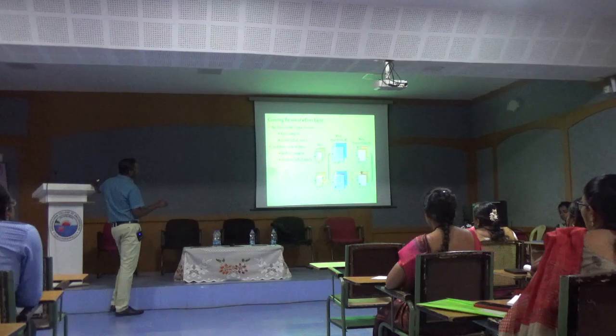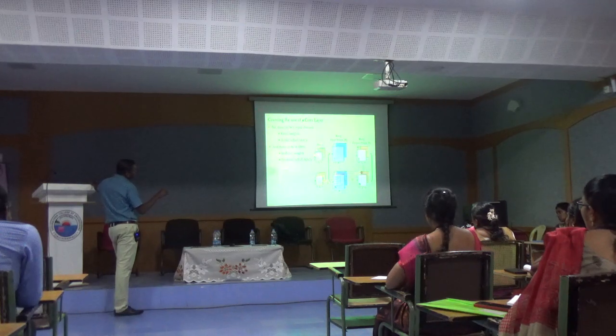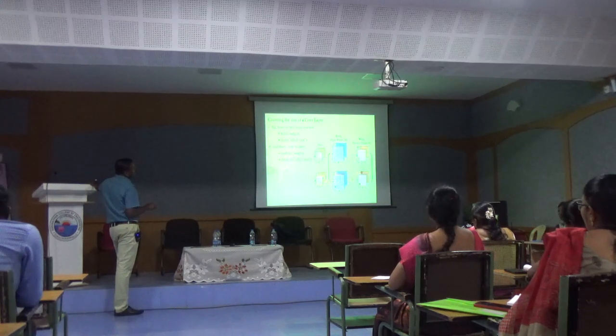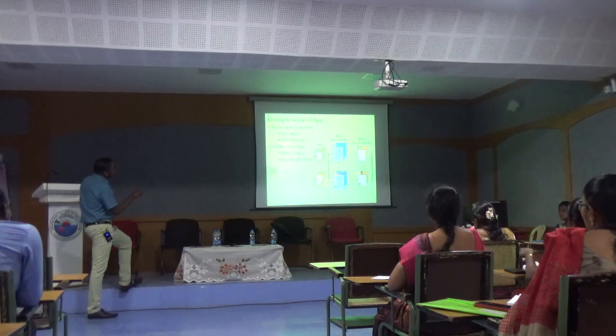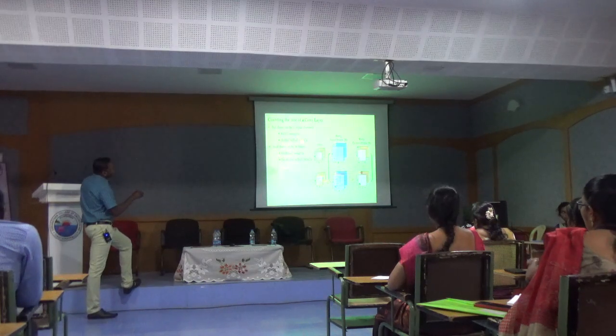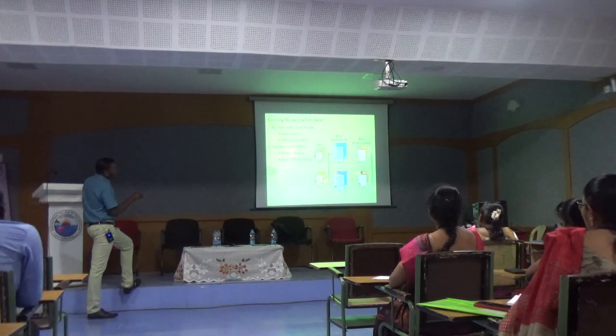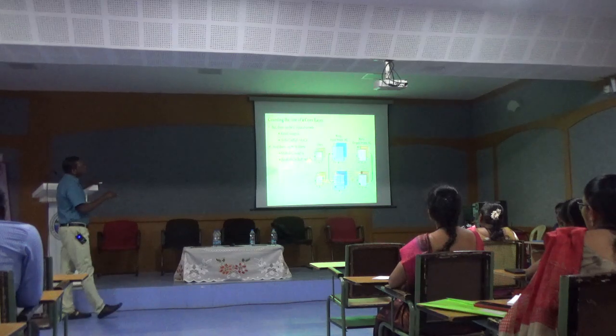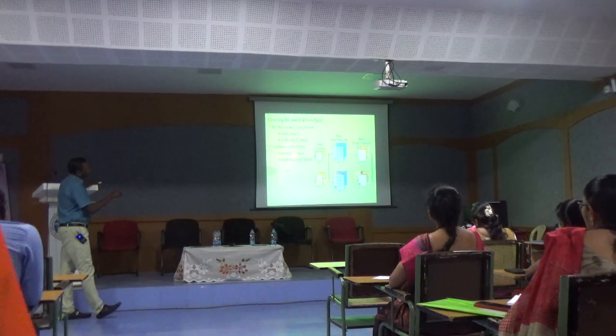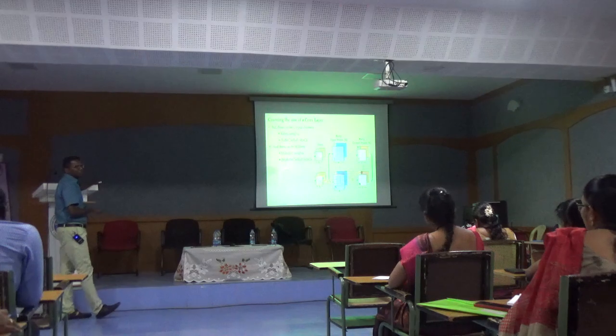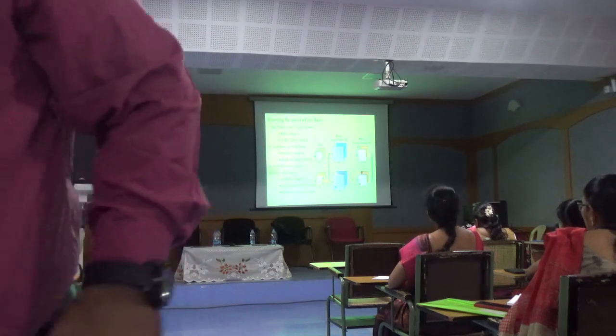So this is how we find out the MACs. So if you look here, you can see that C into R into S such filters are there. N input feature maps are there. Many output feature maps are there. So there will be M number of filters, right? For each map, M number of filters are there. So your final value will be M number of filters, R and S the kernel size, and C the channels. So the total number of multiplications and additions will be M into R into S into C into E into F. So this many MAC units will be there in the system.